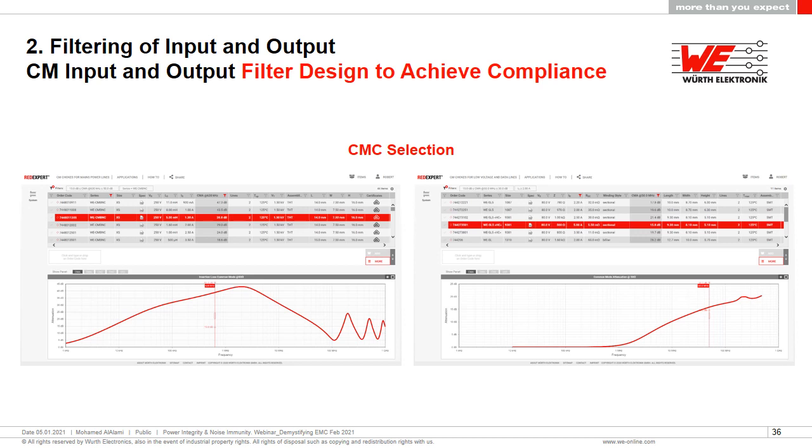What you see on the left hand side is a common mode choke that is made of a material called nanocrystalline. This is a fantastic type of material because it has a relatively wide range of insertion loss. So it's a wide bandwidth material, and it gives me quite a substantial amount of attenuation, particularly at the 630 kilohertz, in this case about 15 to 20 dBs of attenuation.